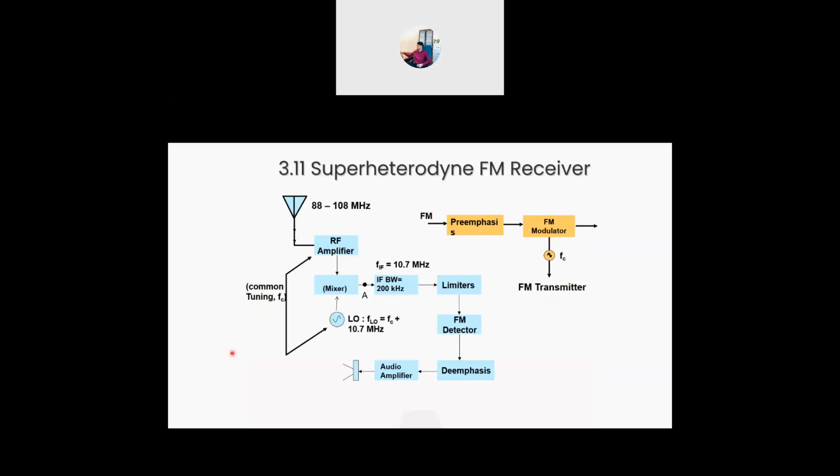At the receiver side, this is the whole receiver. The signal is received here, then we have an RF amplifier to amplify the signal. Like I told you before, the signal is sometimes weak because it has travelled a further distance and been disturbed by multiple noise, fading, path propagation, whatever. That's something not covered in this section. Generally what we receive is a weak signal, often disturbed by noise. That's why we need to amplify.